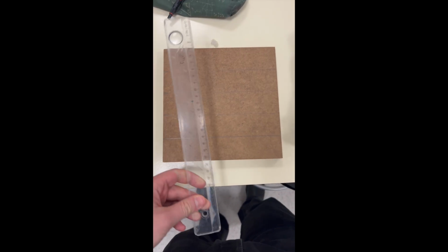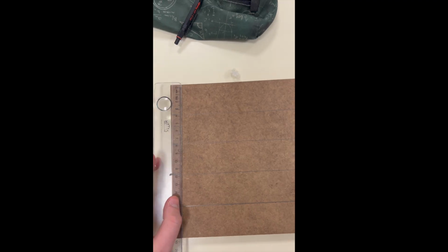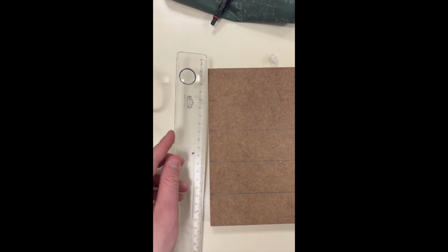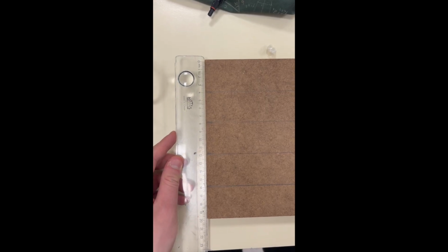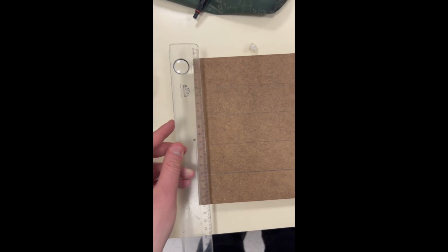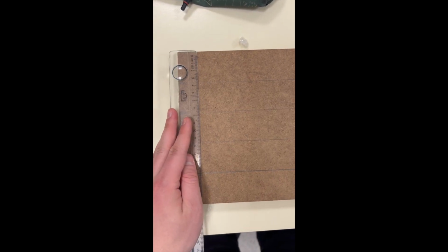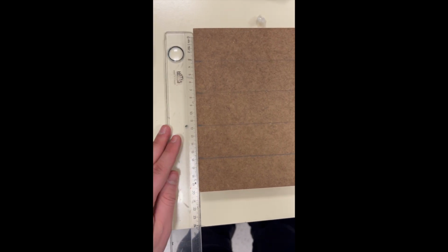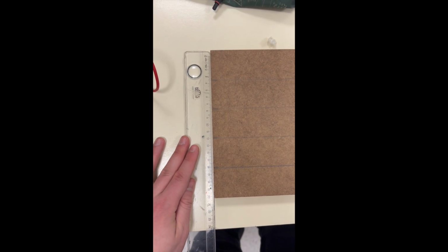First of all, I prepared the wooden dielectric material for the measurements. Firstly, I used a ruler to divide the wood into 4 cm intervals. These markings were important because they allowed me to control the insertion depth more accurately during the experiment. By using equal intervals, I was able to insert the material step by step and record the capacitance at specific positions.